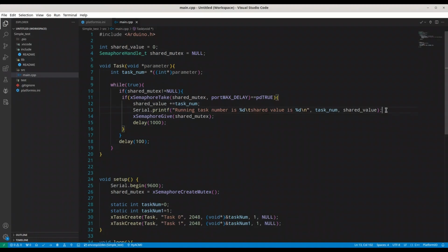Well, as you know, this could be really handy, especially if you are using serial communication between multiple devices. But for this episode, I'm going to show you only the basic principle. So we are going to have two tasks. One is going to write to serial monitor, another is going to read from it. And for that, we are going to use an object of QHandle. And QHandle, it's an essential element of this process. It works like a pointer towards a message object. And the message object, it's actually what holds content that two tasks are going to use for communication.